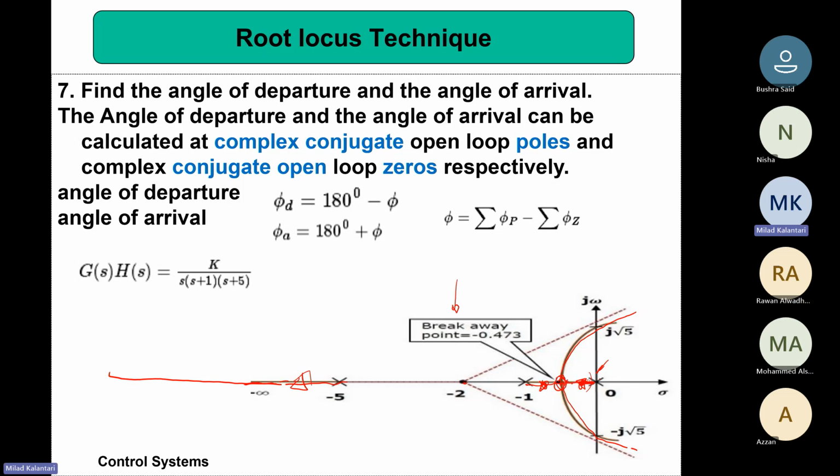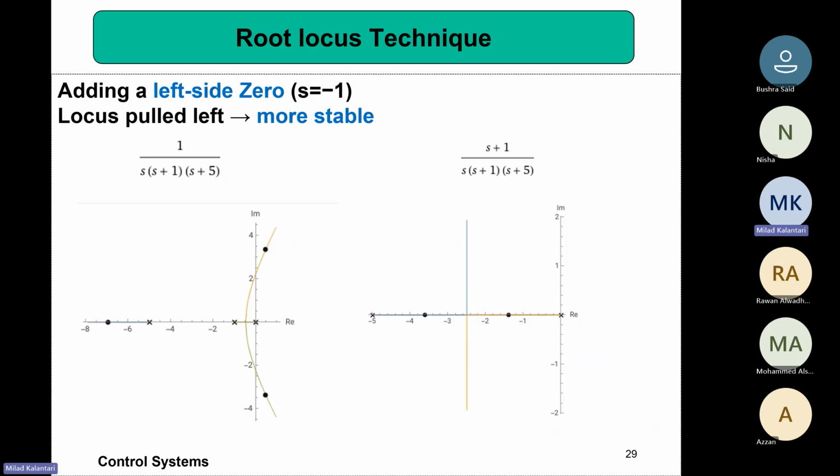And then if you increase k further, you see that the poles become imaginary, right? And then it looks like a second order system at a certain point. If you ignore that the third pole is still far, you can actually ignore it. And then like a second order response, you can adjust it to get reasonable overshoot or damping factor, all of those things. And also, if you increase the K too much, like above 30, then the system will be unstable, right?